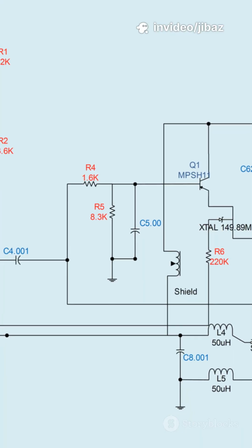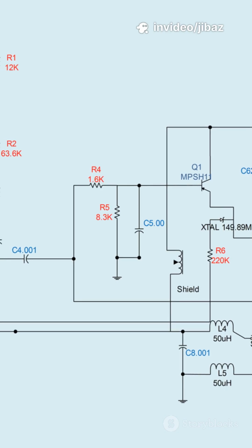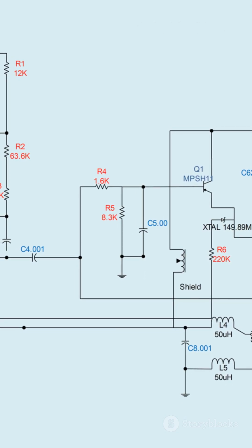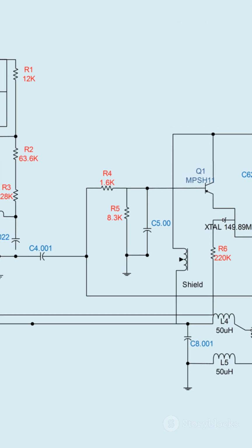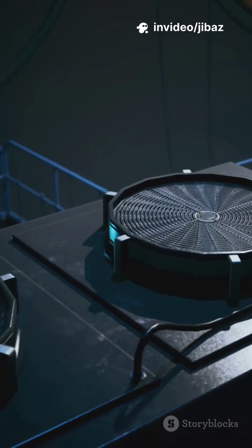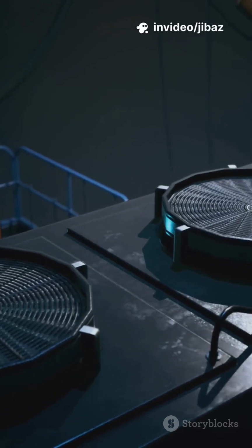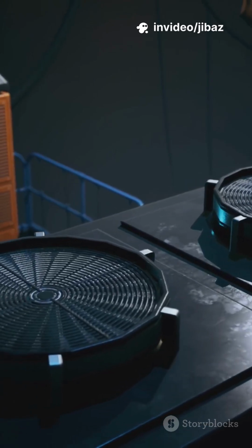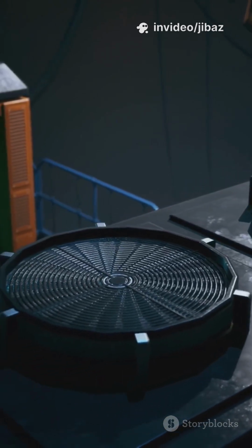And the most common, the bridge rectifier, uses four diodes arranged cleverly so that both halves of the AC waveform are used without needing a center-tap transformer. This configuration is efficient, compact, and found in most modern power supplies. The output, though still pulsating, is ready for the next stage: filtering.